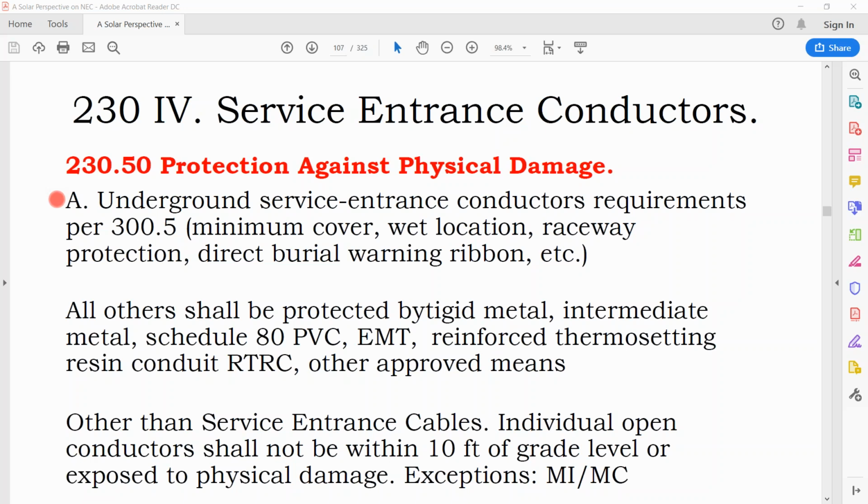Now, you don't always need to have your underground cable in conduit. If you're running your cable under a road where you have heavy equipment driving over the road on a regular basis, then you would be concerned about the weight of those vehicles pushing down sticks and rocks in the dirt and nicking your wires.